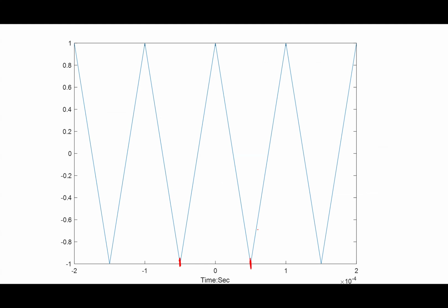All right, now, looking at this guy right here, what is one period of this thing? Can you guys tell? Is it just 1 second? Well, yeah, the reason I wanted to point this out is it has this thing that MATLAB does here. That's this times 10 to the minus fourth. You're right. So it goes from 0 to 1, but MATLAB will do this where it says times 10 to the minus fourth. So it means the period is actually 1 times 10 to the minus 4 seconds.